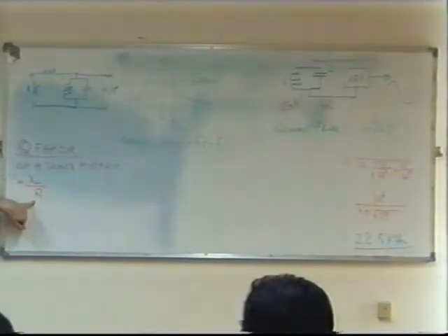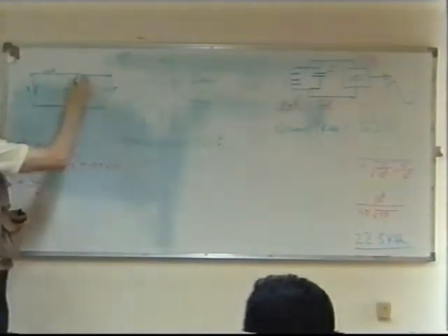Now it's important to understand what this resistance is. This resistance is the resistance of your tuned circuit. In other words, it's not this. It's the losses here. Not Z. Z is the combined impedance of the tuned circuit. R is resistance, in other words the resistance of the coil of wire.